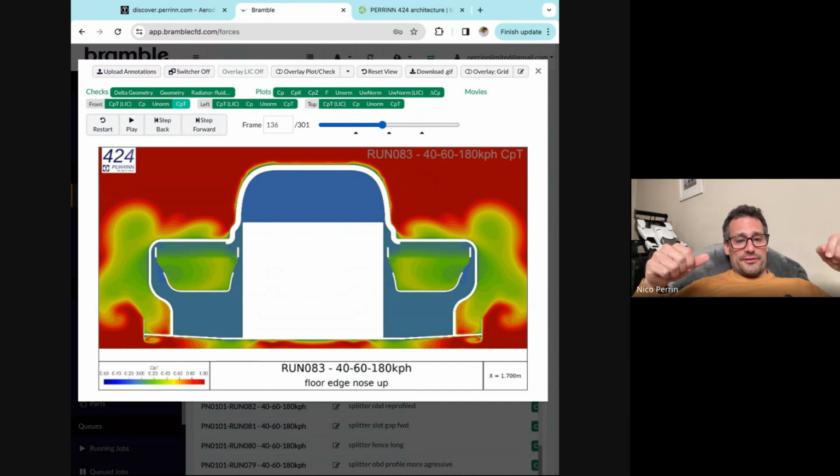And actually on F1 cars as well, from the second part of the diffuser, it also comes from the sides, purely because there's a lot of suction and a lot of air needs to go there, and it needs to come from somewhere. And so what you find is you're not really deciding that the car is going to work like this. What you're observing is that the flow structure is working this way, and all you're doing with development is making the best use of that structure.